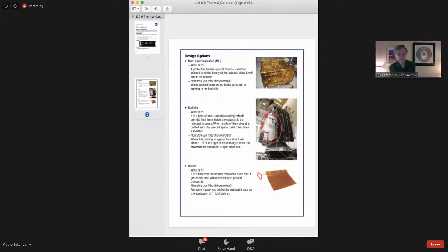Now, the next thing on that page is a radiator. Remember, I said that white paint was good at radiating in the infrared region, which is what we hope our spacecraft are at, that temperature, more or less room temperature. So we use that to send the heat out.